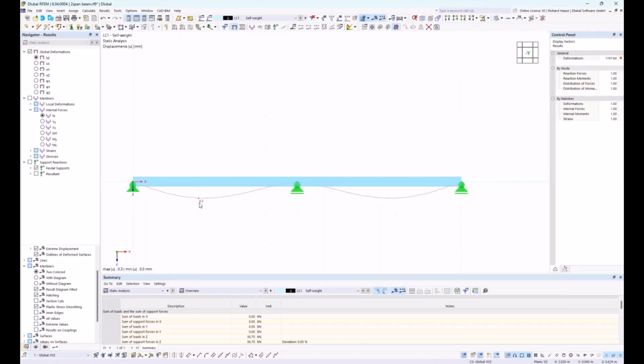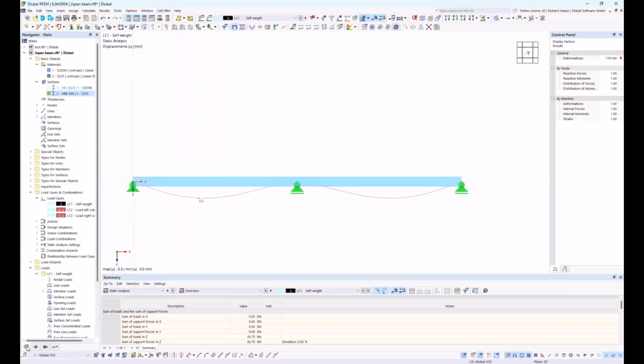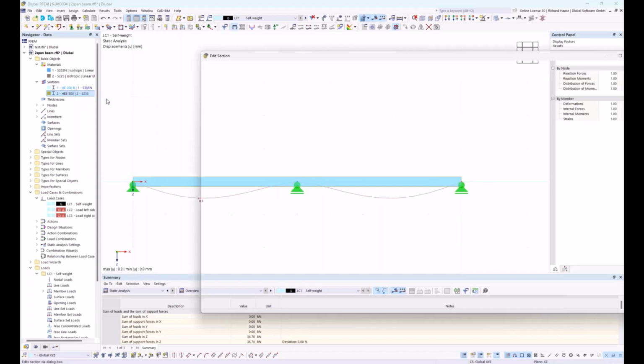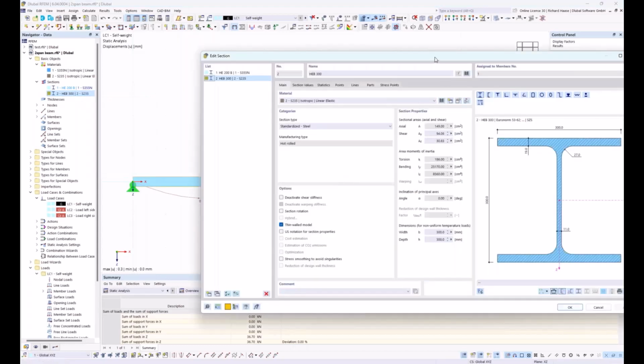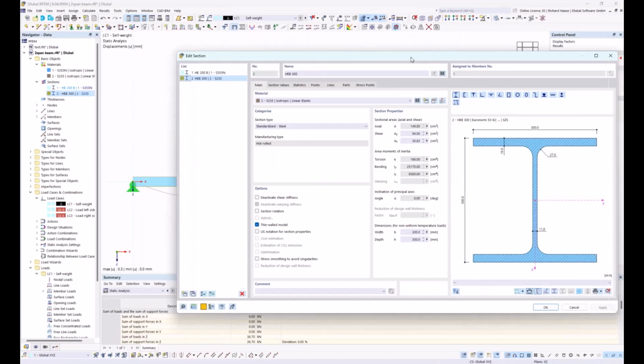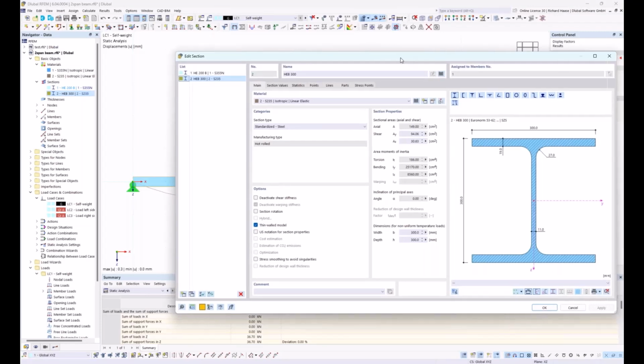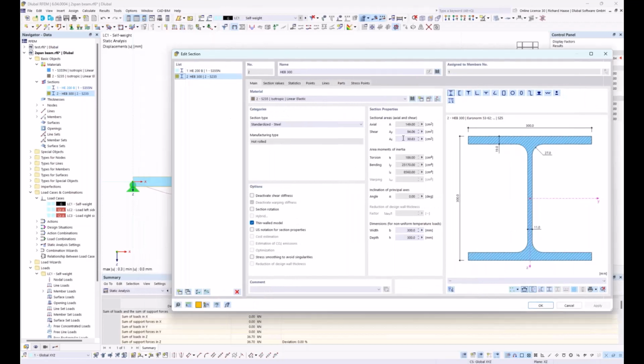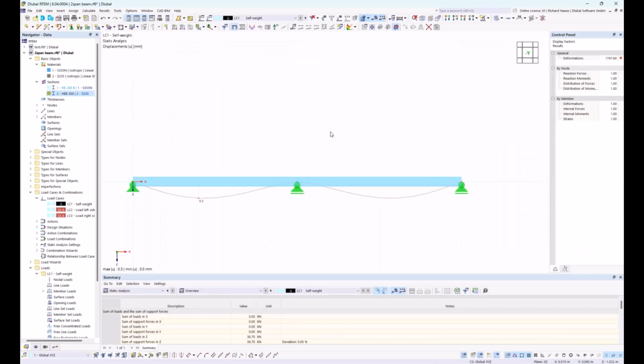So you see it's changed from 0.2 to 0.3. So the deformation is bigger because the shear stiffness is making the system softer. So you must, when you make control calculations with literature or so, most of the time the shear stiffness is deactivated. Okay. Yeah, then okay, let's calculate.